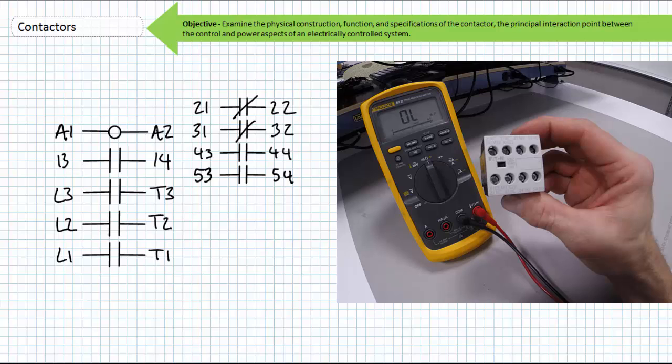These auxiliary contacts are rated for the switching of control signals, not power. These contacts are extremely useful for advanced control purposes, such as an electrical interlock, which prevents the coil of a contactor designated for reverse rotation from being energized while the one designated for forward rotation is energized. We'll discuss reversing motor starters with electrical interlocks in later lectures.